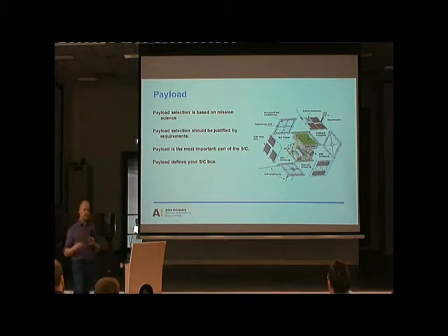The satellite is giving energy for the payload, it's giving downlink for the payload, it's giving maybe attitude control for the payload, and it gives the thermal environment for the payload. So the whole mission is driven by the payload.